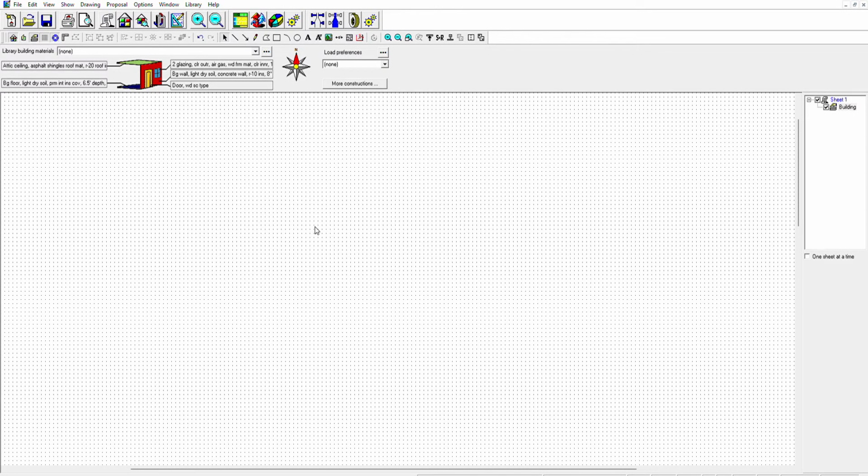Now what we're going to do is a quick example on how to do some rooms. So we're going to draw a room. Let's go here, and then we're going to do this. So for example, if we have in here, this is for residential mainly. This is going to be the kitchen. Okay, kitchen. And if you want to put the properties, you click and then you right click, and you're going to be able to see all the properties in here.